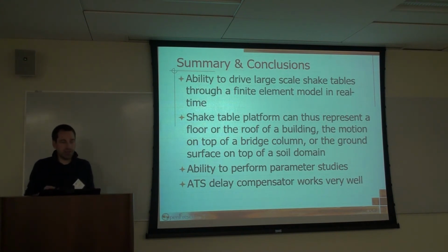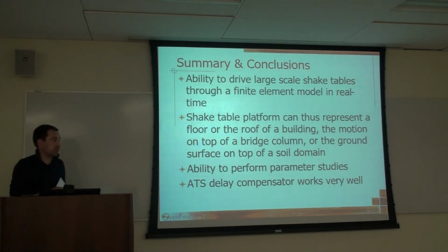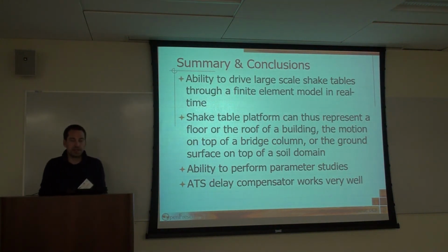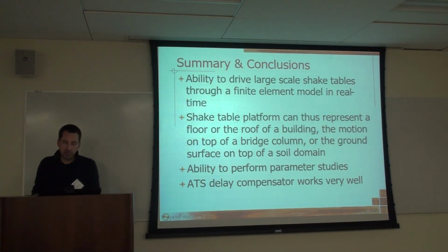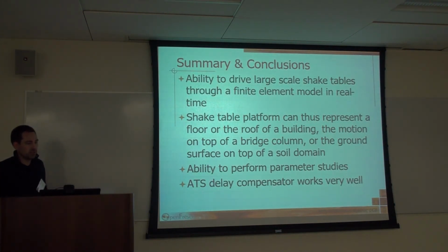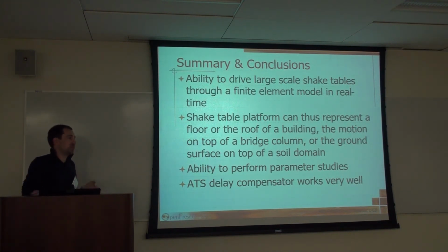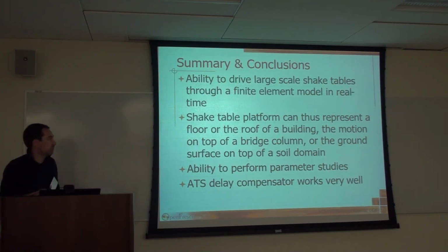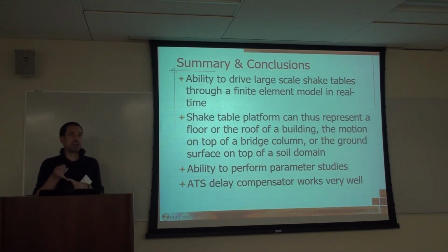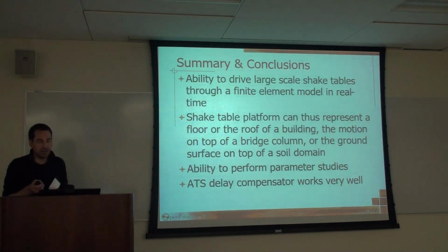I showed you that we have the ability to drive very large shake tables, and we've done it many times on different tables through finite element models, and we can do this in real time, as we have to do for a hybrid shake table test. Shake table platforms can also represent floors and roofs of buildings, and the top of the motion of bridge columns can also be done. Or we can do it at the ground surface, where we have a soil domain numerically modeled, and the shake table represents the ground surface on top of that numerically modeled soil domain. We have the ability to do parameter studies through this, and also the ATS delay compensator, one more time, has worked super well for us, and we're very happy with that.